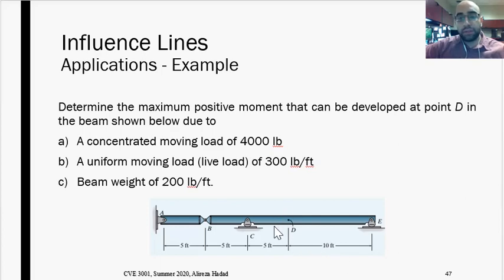How can I draw the influence line? We can quickly use Muller Breslau's principle for that. Based on that rule, I need to remove the restriction for that specific force or moment and then apply a uniform deformation and see the deformed shape of the structure. Once you do that, the deformed shape will be the influence line diagram.